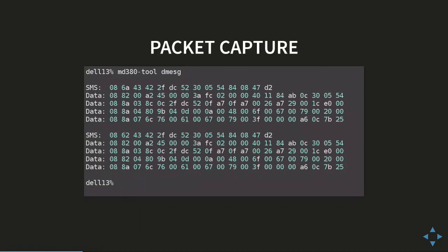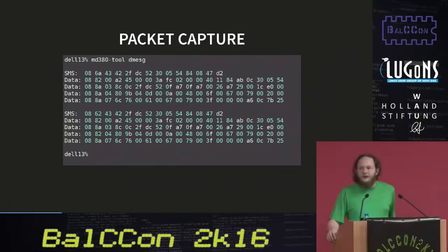But it's not encrypted. Even if you enable encryption for the channel, the Tetra radios, the ones that I've been reverse engineering, leave all of the encrypted traffic clear text. The same thing happens with audio for all of the metadata. So even if you couldn't break the crypto, you would still see what my source address was and what my destination address was.